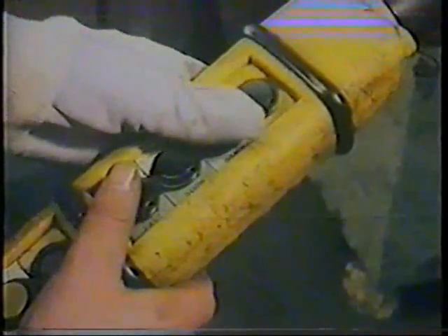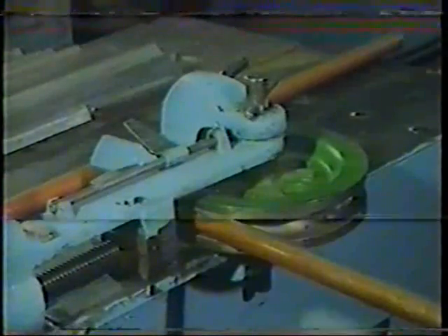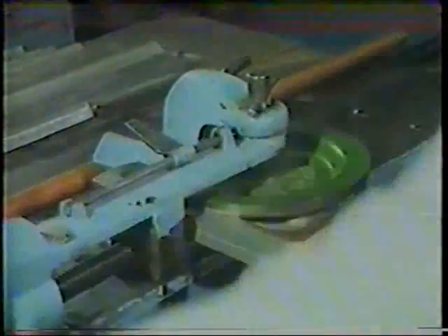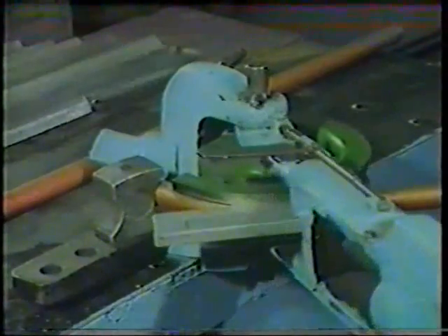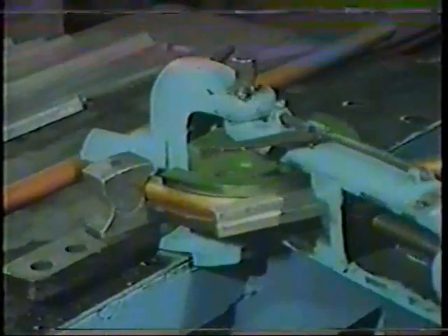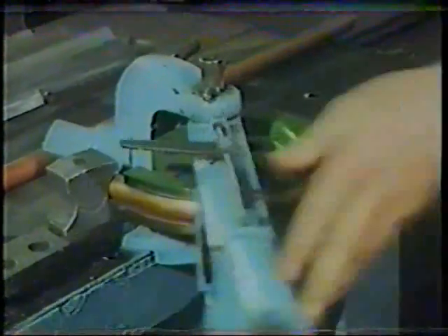It can be cooled quite quickly with water. Annealing has increased the ductility of the copper and reduced its hardness. Now it can be bent without fracturing.